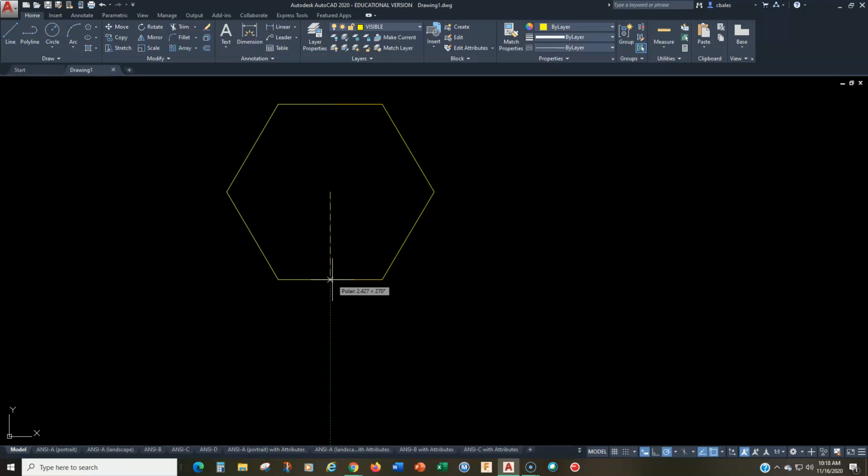I always get drawings that students turn in that have the hexagon given with the wrong dimension here. So pay attention, people. We're going to use my trick, which is apostrophe cal. So I type in apostrophe cal. You can see it right there. Hit enter. And I'm going to type in 1.75 divided by 2, because that's half of the width. Put that in there, and there we go.